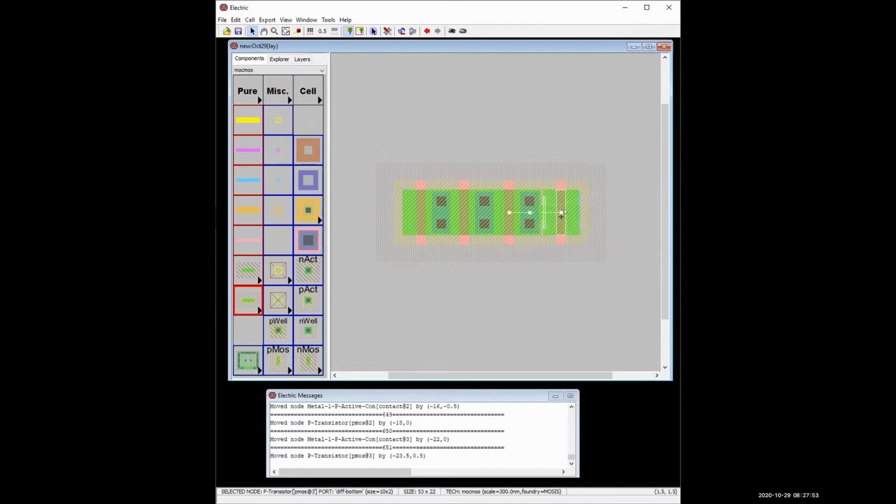Why do you have 4 transistors? Delete the one on the right. Hit F5. 0 errors. So it was all about those notch runs. Effectively, it was saying that the run between the two pieces wasn't wide enough. But when you overlay everything like that, it gets rid of it.